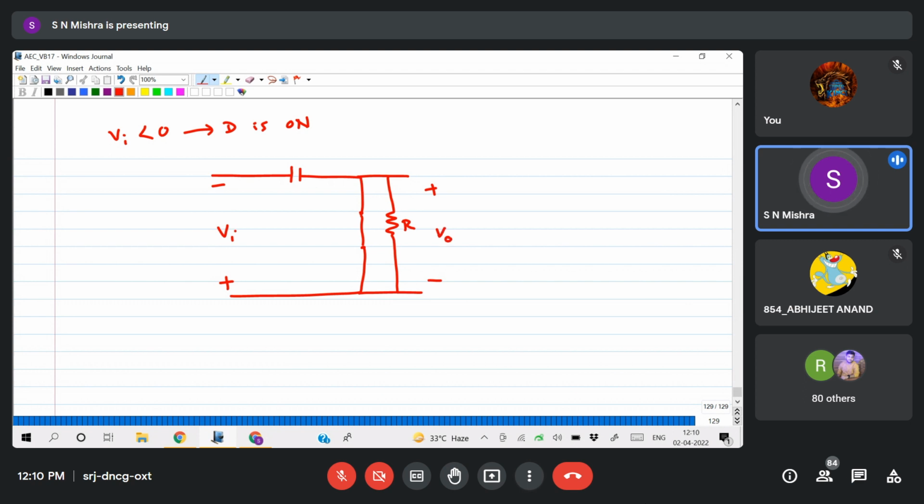Here across the capacitor, you can take two things. Because this is a negative sign, I can take this minus, this plus, and this is VC, or you can also take plus minus. I'll come to that a little bit later. So this is a capacitor. Then apply KVL in the output loop. Minus to plus, plus V naught, plus short circuit 0 equals 0. So V naught equals 0.